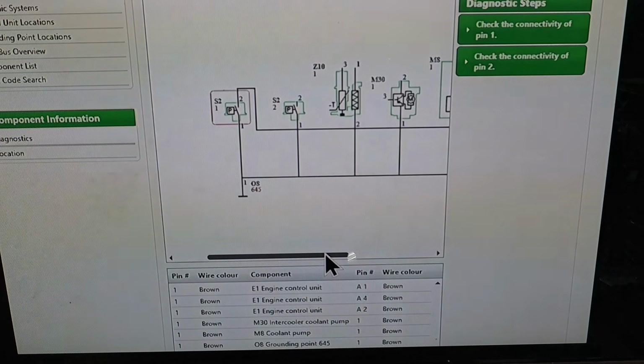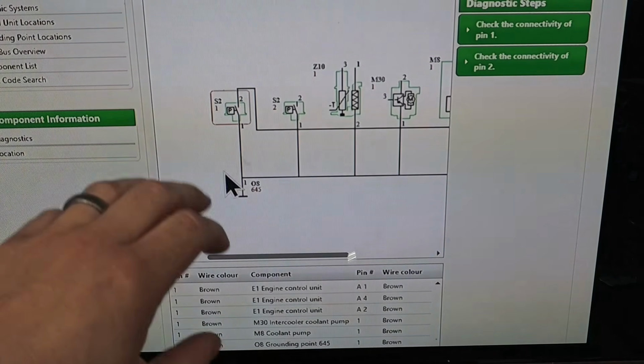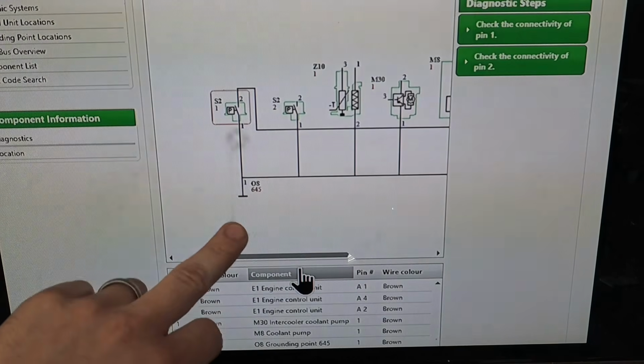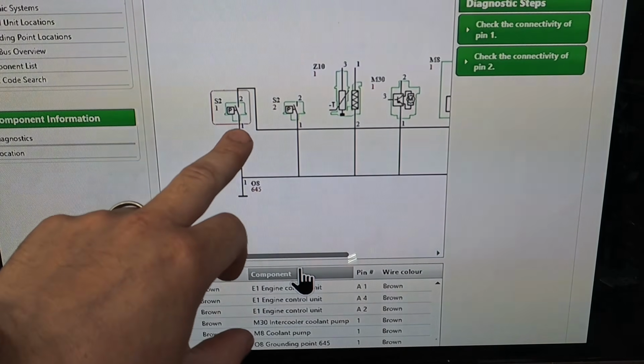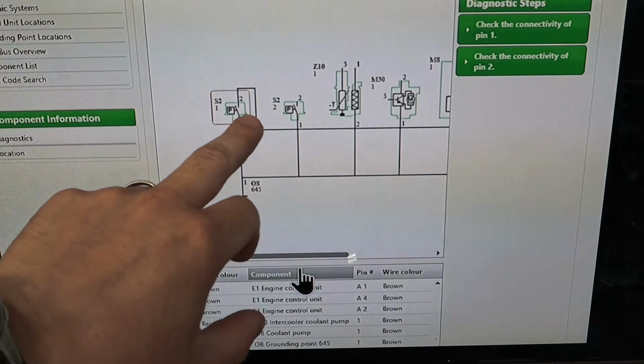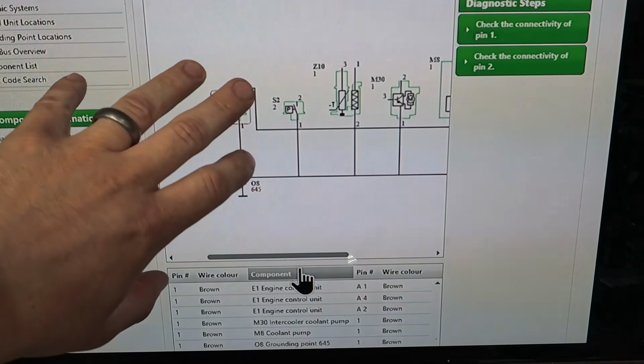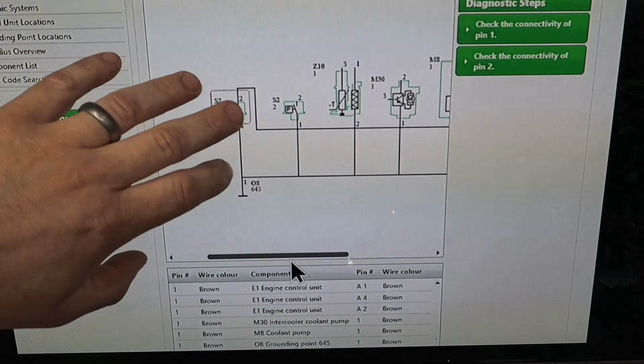Now, basically how this is going to work is you're going to have a low pressure oil pressure switch and a high pressure oil pressure switch. So our management system or technical data will tell us that oil pressure should be within a certain realm at a certain rev range. So assuming this is the low pressure one, if this gets to like 1 bar of pressure, it will close that switch, complete the circuit, switch the light out and say that oil pressure at that pressure is okay.